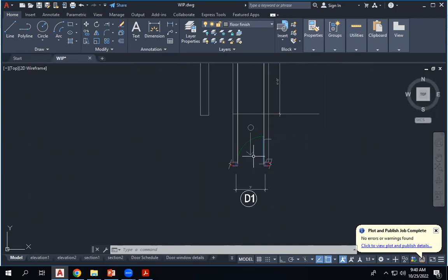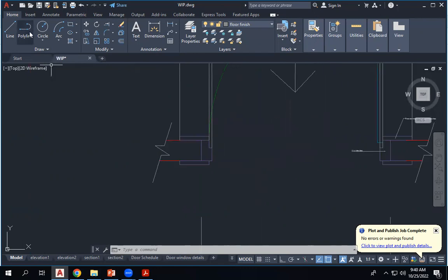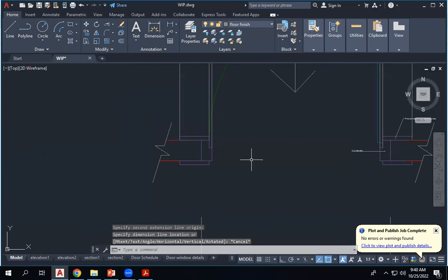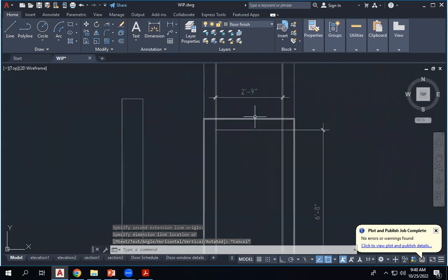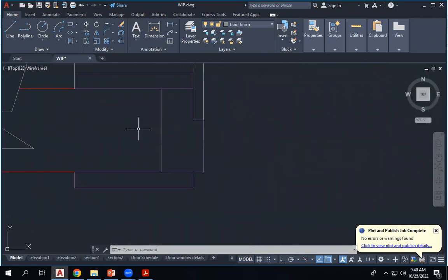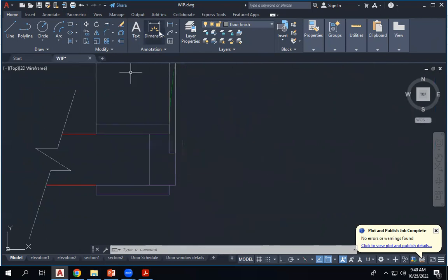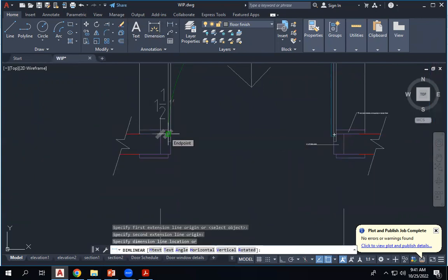But when that person is doing the frame and the door, he will also take the structural opening, and according to the frame size, he will take the panel. But you need to give also the panel width as well, like this 2 and 9. Then the person knows that from the 3 there should be 1.5 and 1.5 to put into the frame. See here now, it will be like this. Yes.